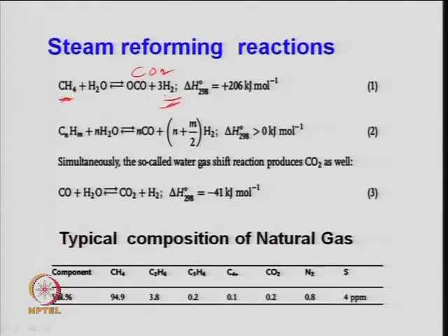So, basically the other option is syngas also, where you have the partial reforming and partial oxidation also sometimes. So, that gives you the syngas also, that can be used for liquid fuel production or alcohol production, and widely being practiced. Fischer-Tropsch type of reaction is used there also, right. So, any hydrocarbon again here, not only this methane natural gas. So, what I said, naphtha is also being used, right.